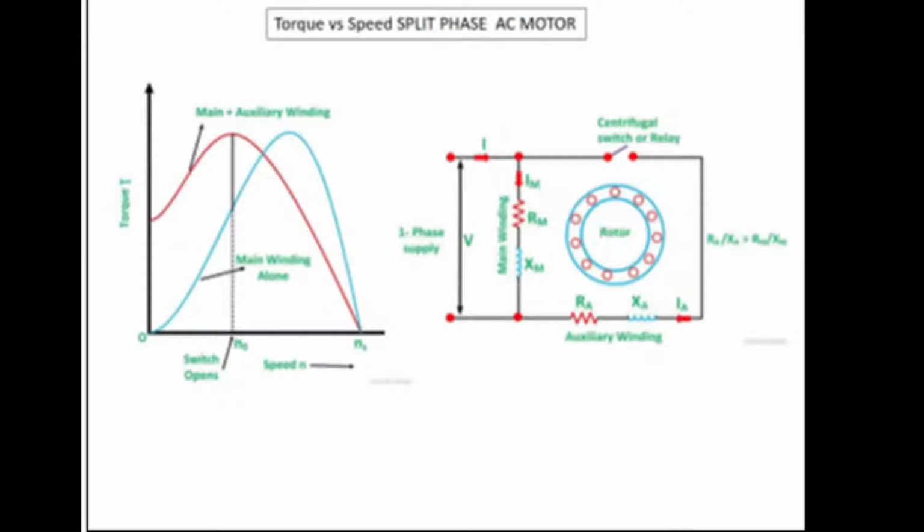Here we have a split phase motor circuit, as shown on the right hand side. The schematic shows that when we apply the single phase voltage at the top to neutral at the bottom, we have two coils that are in parallel, the run coil here on the left and the starting coil here on the bottom. With a split phase motor, the resistance divided by the reactance of the start coil is always higher than that of the run coil.